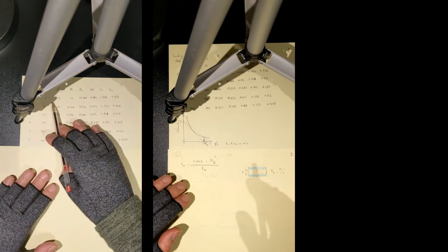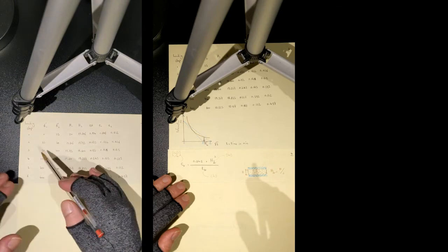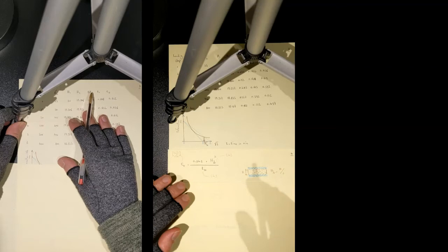Now, I'd like you to look into each of these loading steps. For each of these loading steps, the soil is kept under load, under pressure, for 24 hours. And yes, I can see this delta H, which is the final settlement of the soil after 24 hours. But in fact, you can measure the variation or evolution of delta H with time. And if you do that, you can get this diagram that I presented initially by mistake.